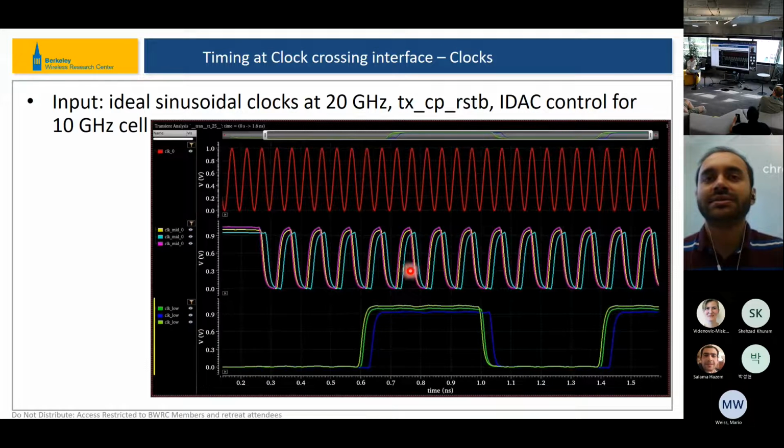And by running the simulation on that, now I can see across 3 corners what the clock phases look like for the different frequencies. So this is where the partial layout generation helps us to simulate certain blocks while taking into account the top level routing effects.